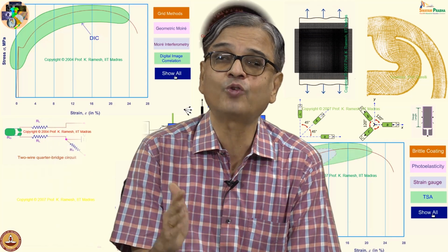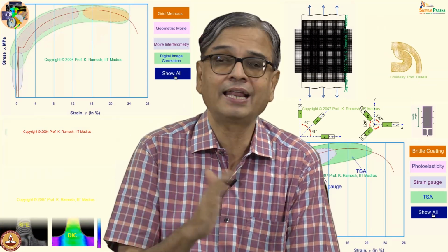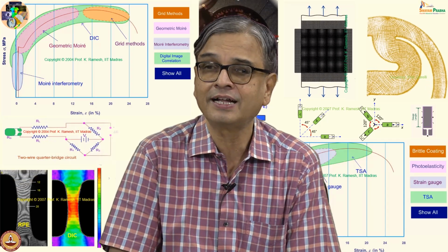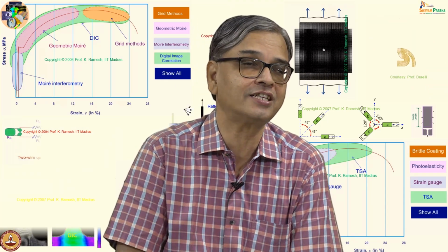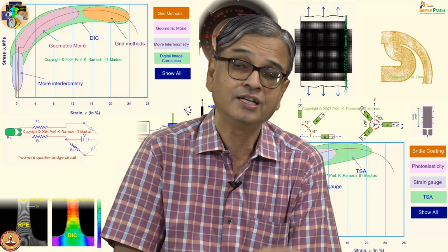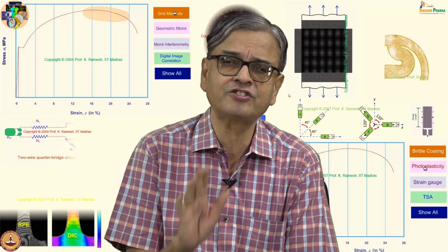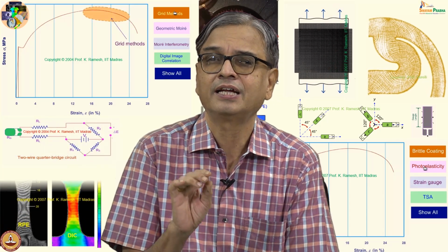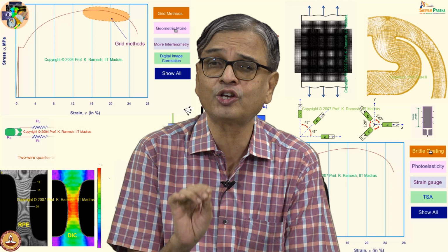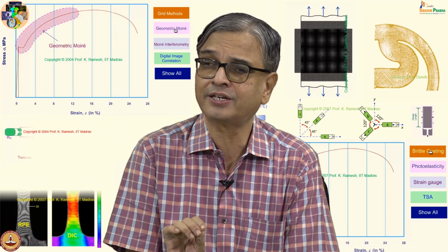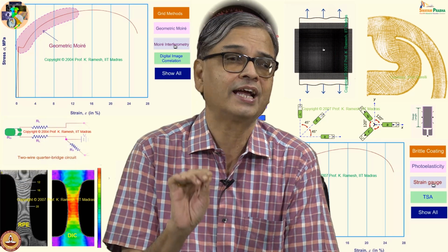Don't simply use whatever strain gauge is available at the 11th hour, plan and then try to make the measurement, and finally blame the technique that the strain gauge technique is not giving you correct results. It's a very sophisticated technique. You have to be sensitive from the first stage of the experiment and handle the technology, listen to all the manufacturer's recommendations, paste the strain gauge and make the measurement.